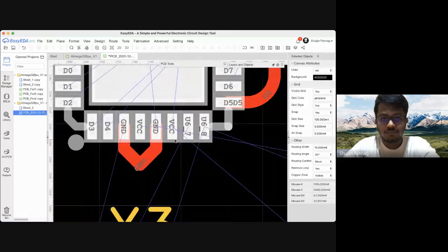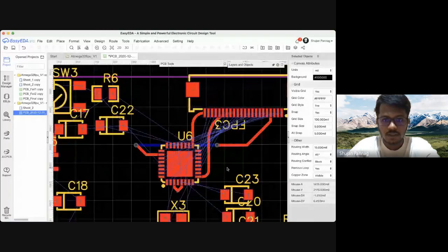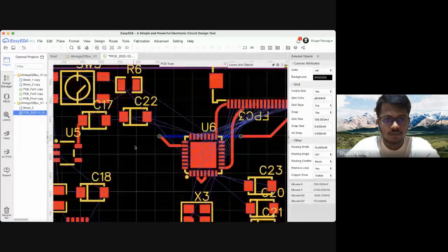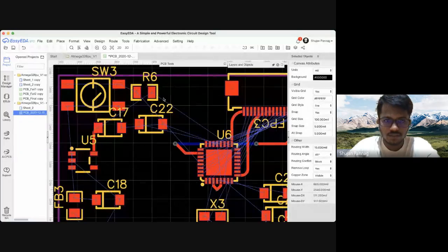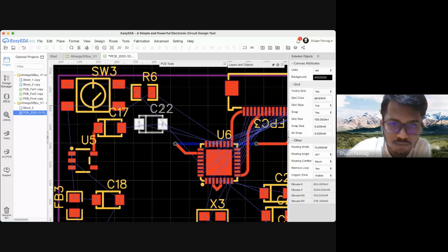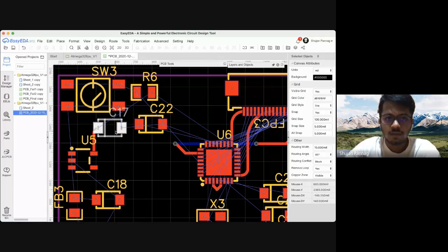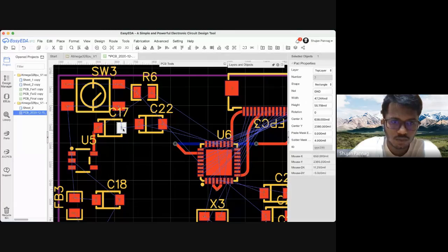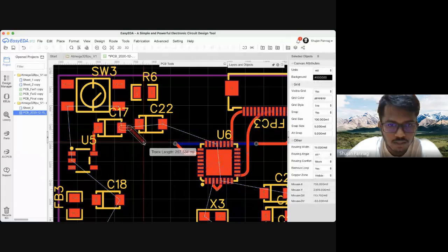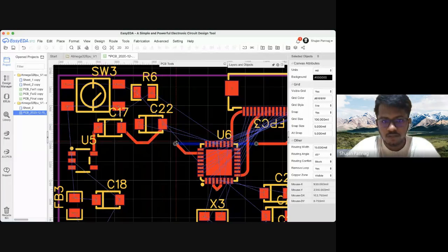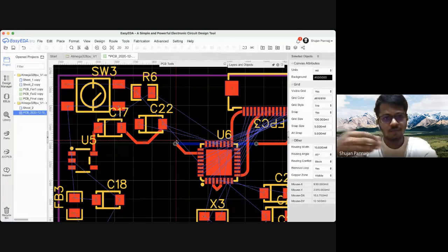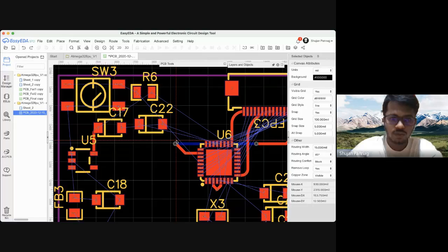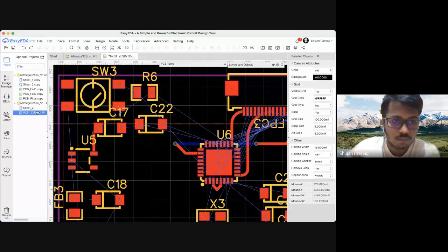So that's why you use vias. Another thing would be, these are called air wires. These are wires that help you to route it, but they are not actually connections. And then what I have actually done is, in Mano's circuit, he connected all the grounds to the grounds, right? So if this is a ground, he connected it to this ground. But I won't be doing that. I just told you that using a ground plane is the shortest impedance path for all the return currents. So what I would do is, since this is not completely routed, I'll go to the one that I've completely routed.